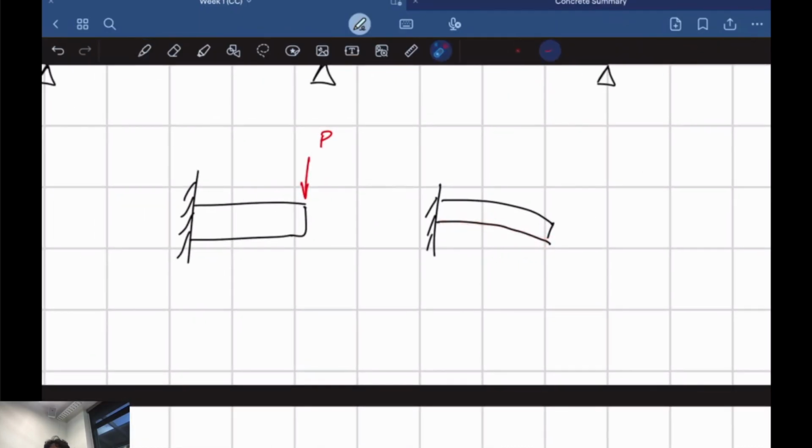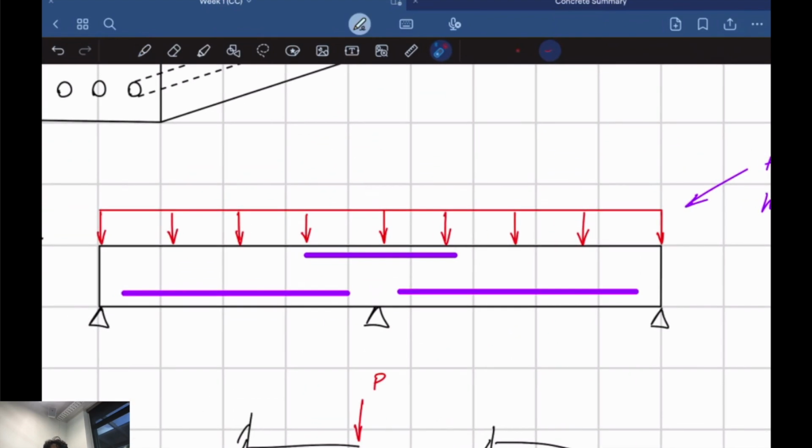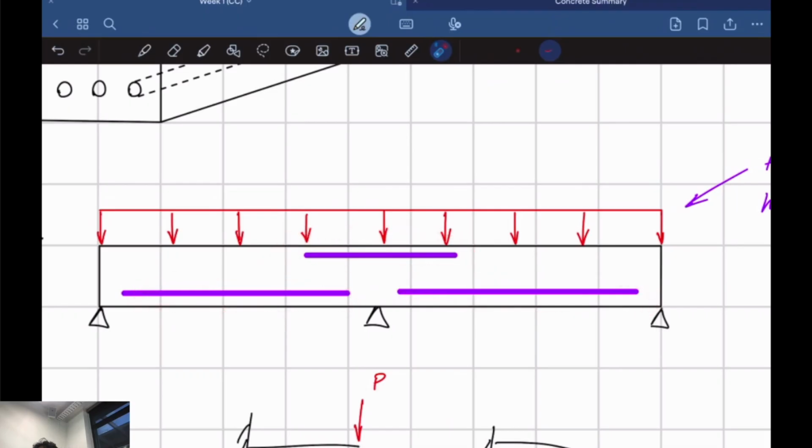You know how we have it for the beam above, there were two at the bottom and one at the top? Wouldn't we have it mostly at the top and then at the bottom when it's in compression? No, you only put it where it's in tension. So the top's in tension, yeah. It's in tension here and at the bottom it's also in tension. So it's in tension here, here, and here. Makes sense. Okay. Beautiful.